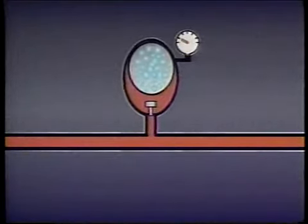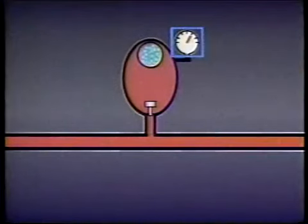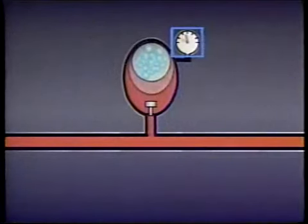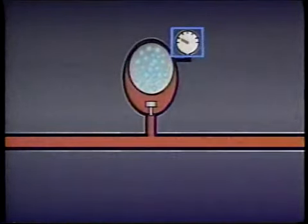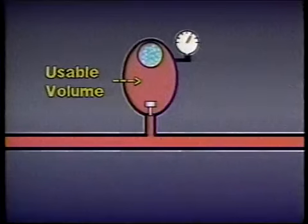To develop flow or to maintain fluid pressure, the accumulator must be filled with fluid until the nitrogen pre-charge reaches a specific maximum pressure. Then, as the system requires flow or pressure, the accumulator discharges fluid until the pressure of the pre-charged nitrogen drops to a specific minimum level. The volume of fluid the accumulator discharges between a maximum pressure and a minimum pressure is called the accumulator's usable volume. The usable volume in an accumulator depends on how quickly the accumulator is filled with fluid, how rapidly it is discharged, and on the pressure of the pre-charged gas.